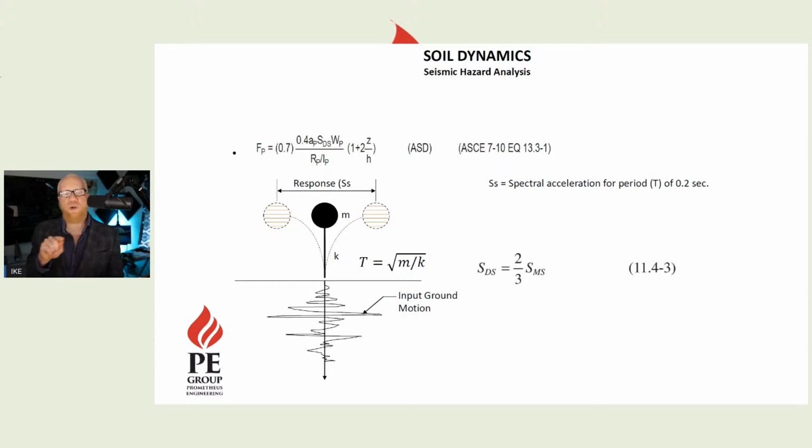But how do we come up with the ground motion for all the sites such that then we can map this thing called the spectral acceleration? So remember, the spectral acceleration is not just the motion of the ground. It is the response of a single degree of freedom, little lollipop that I show on top of there, single degree of freedom structure with a particular frequency, which we plot, to an input motion, right?